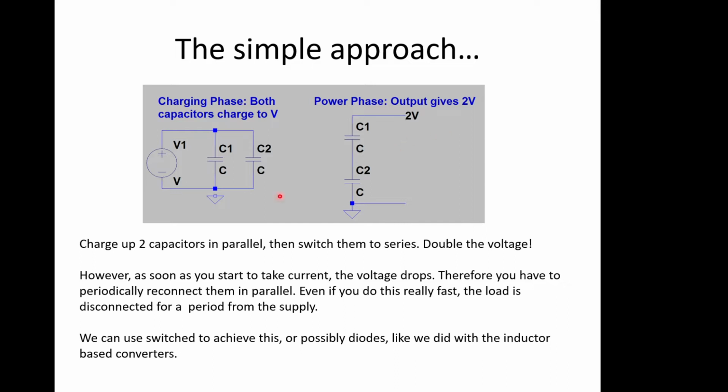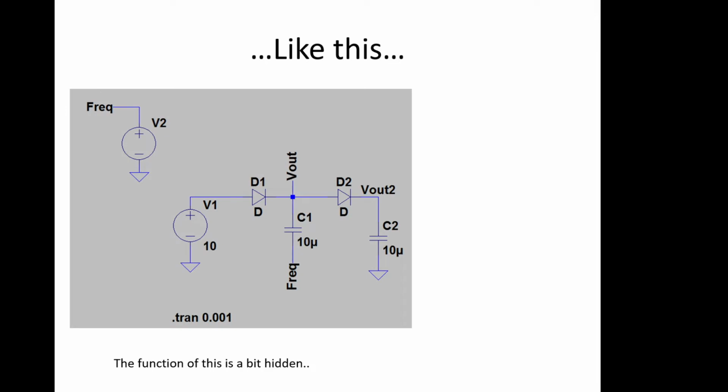So we can use switches. We can maybe use diodes like we did before, but that's fundamentally the kind of idea that we're going to be pushing here. Charge them up in parallel, switch them into series, and it's clever ways of doing that that dictate how this happens.